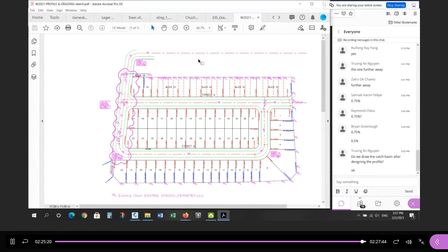Okay. Now I know you're just going to put that aside until you hand in your assignment, but that's good for what we want to do next. Actually design the road profile. So the concept of the design is there. I've given it to you as a hand sketch. I've given you more information here, and then I'll show you the final input on screen in Civil 3D next week. Okay, and that's the beginning of the design, the road profile. Without a profile, we can't do a corridor, we can't do the lot grading, we can't do the road pipes. Okay, so same order of operations that we followed last semester, just a different set of starting conditions.